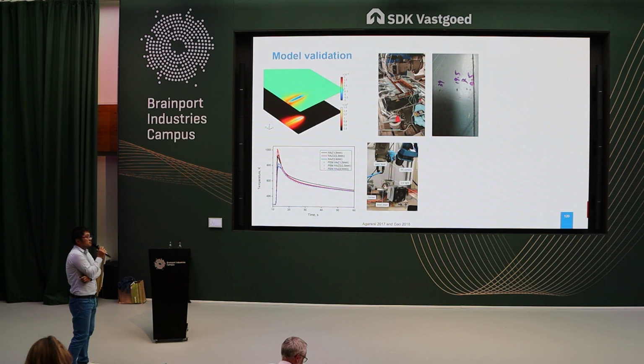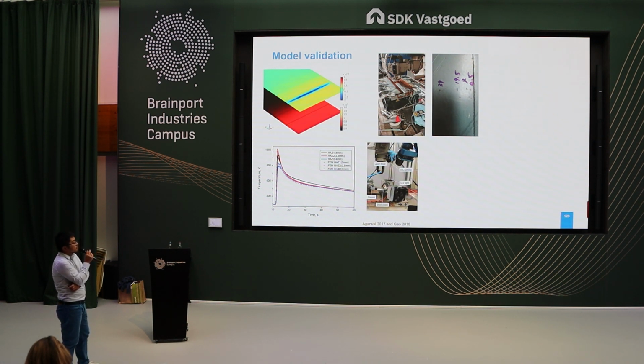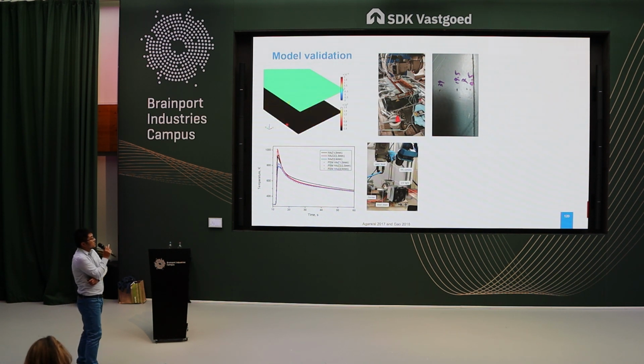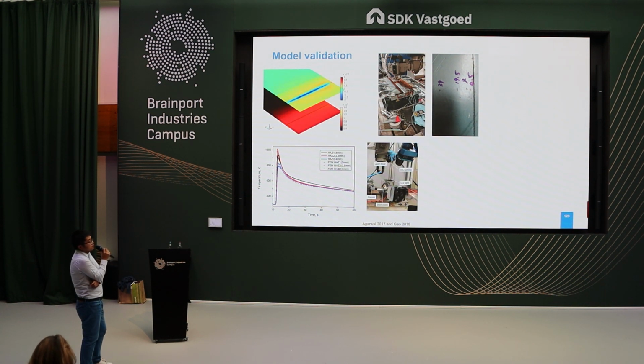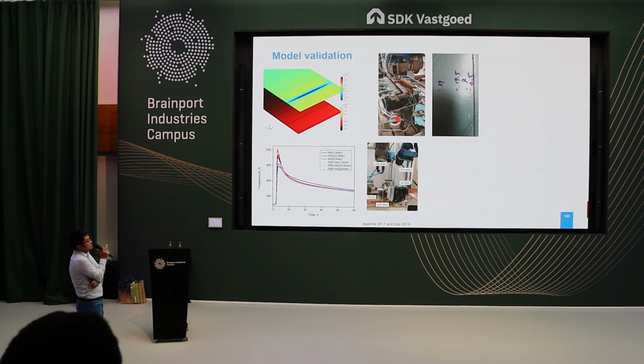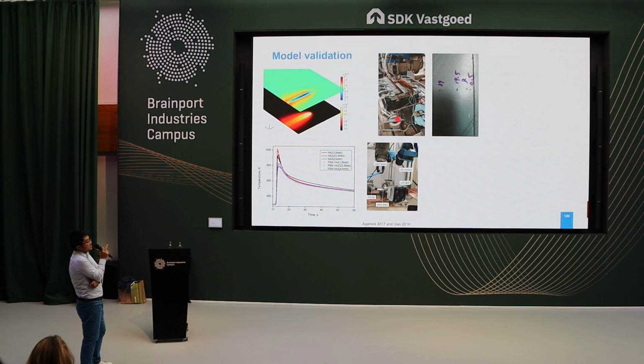Now I talk about how to measure the strain during welding. Actually, from this image, you can see that there are two cameras placed there. But I think most people may think this is just a normal digital image correlation approach. Actually, it is not. Just imagine that during laser welding, the laser plume is so bright that basically these two cameras do not see anything.